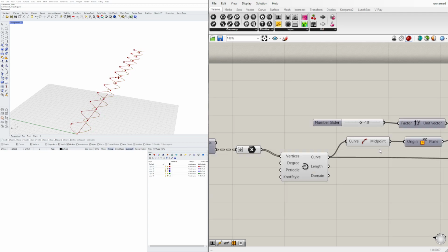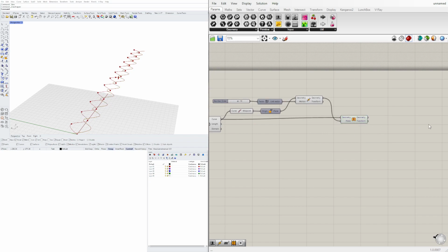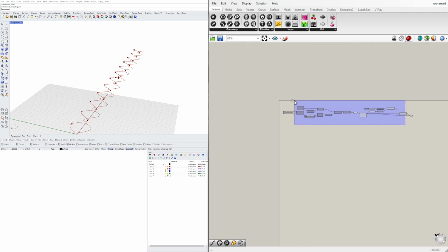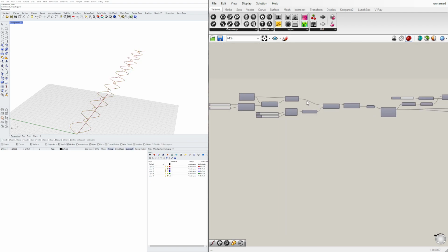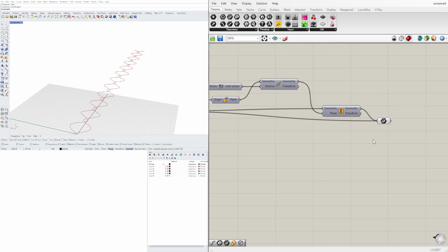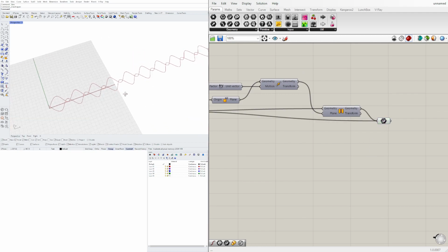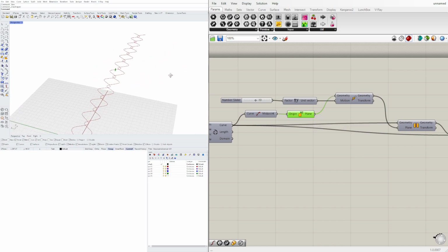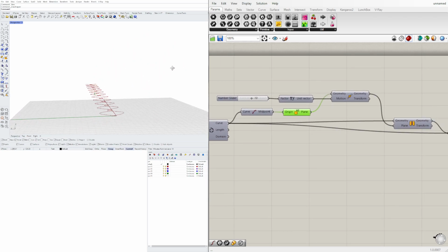little bit. And now at the end here, we can bring in those two curves together. So I'll go to a curve component and plug in both this geometry, and holding down Shift, I'll add this one. Now I'll disable the preview on all of this. So far, so good. So now we still have our YZ plane that was before we moved it.